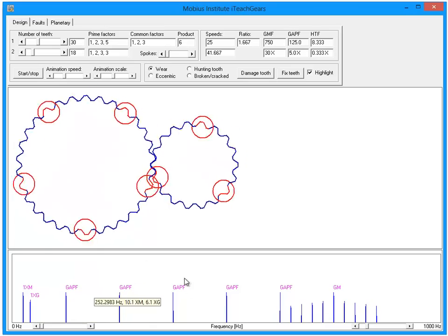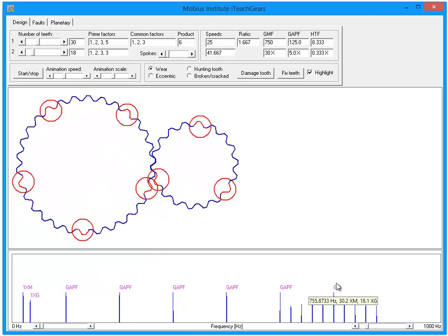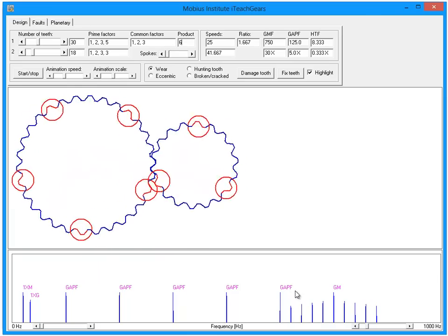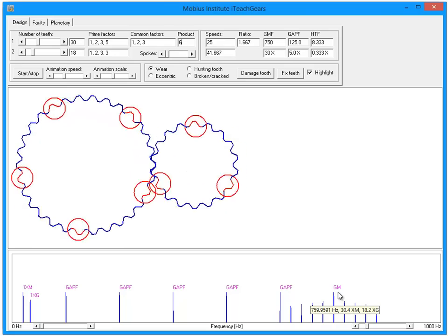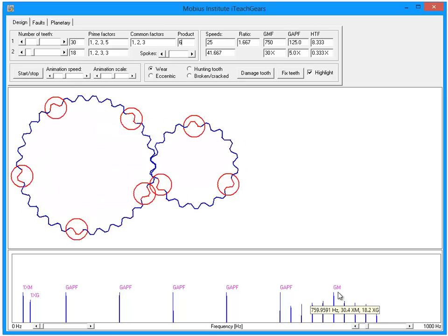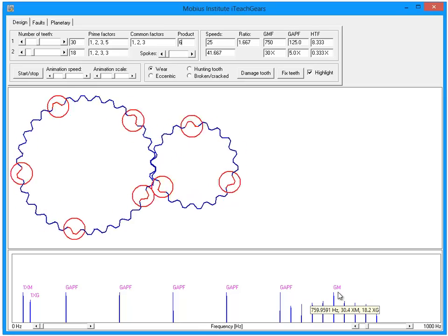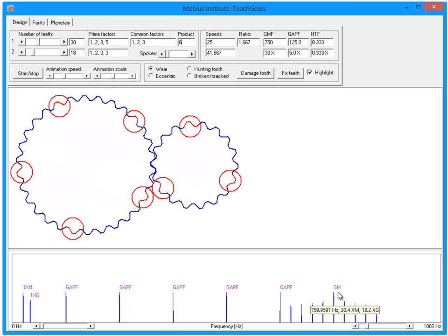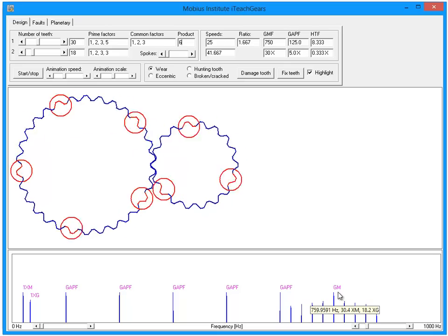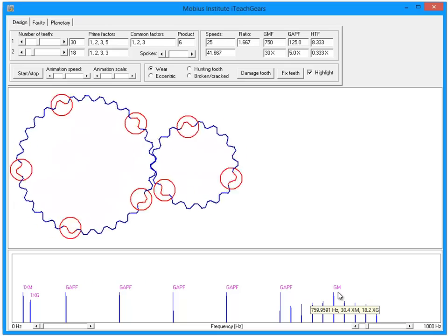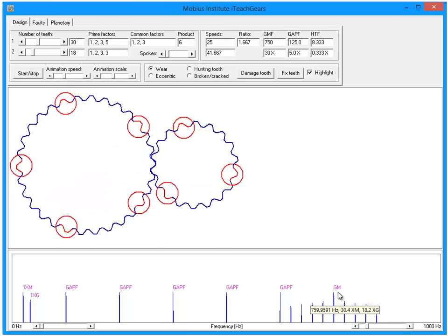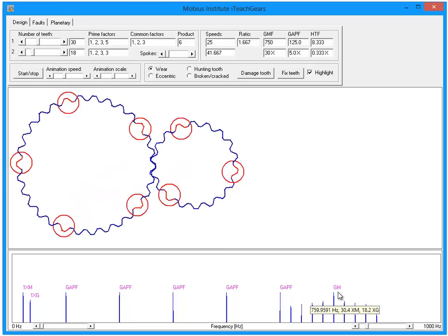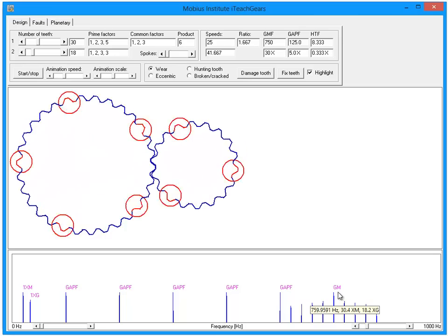And we got harmonics of it. Of course, there's 6 harmonics. 1, 2, 3, 4, 5, 6. Anyway, all the math works out. The point is you can see these peaks. Now, as I said, ideally a gearbox will be designed with a prime number of teeth. But if there's a specific design that was required, there may not be a combination possible with prime numbers. So they have to use these non-prime numbers of teeth, and therefore this is a source of vibration that you may see.